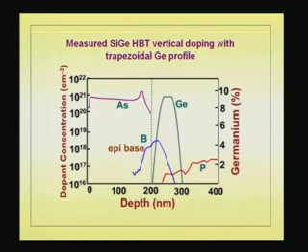Doping profile, I will just quickly run through this because there is no more explanation needed. This particular structure that is used here does not show doping concentration changes: arsenic emitter doping, base doping gradation, and germanium. They have not shown that gradation that much in this case, but you can see from here to here the gradation is there. Germanium gradation is there, that is, band gap is varying from larger to smaller value the other way. There is a built-in field coming up. Okay. And percentage of germanium is right up to about 10%, 0.1. So, band gap is narrower compared to silicon.